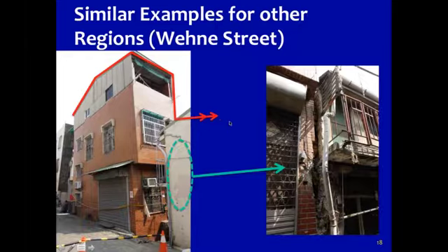If we take a view behind this building, we can see what occurred due to the liquefaction induced ground failure at the front side of the heavily loaded damage. We can see that a large separation between the 2 buildings developed due to the shear strain that needed to develop or needed to be carried as the building moved to the left of this image. So again, seemingly an addition, but a large, heavy discontinuity, geometric and weight discontinuity promulgating into structural damage.